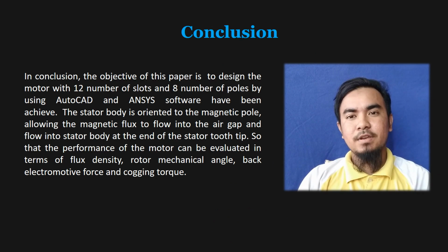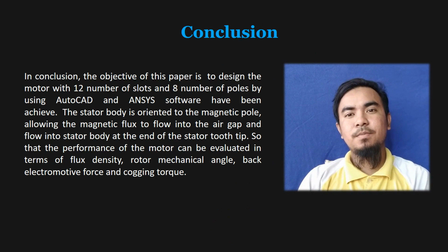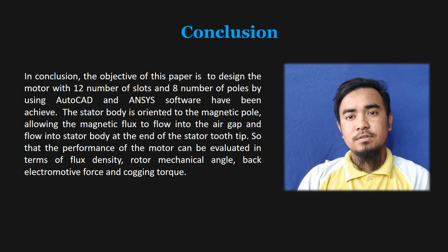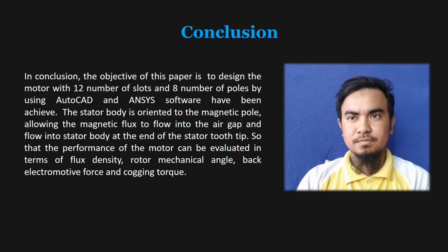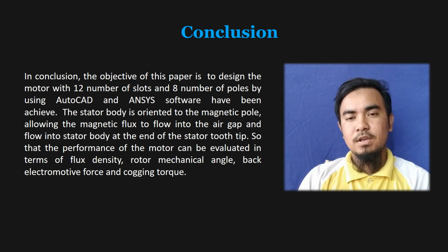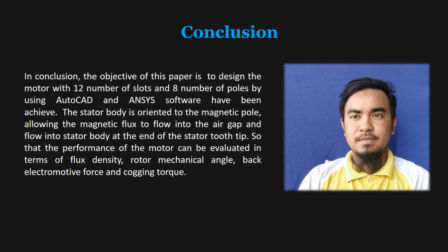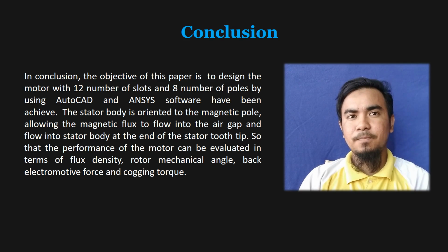Conclusion. In conclusion, the objective of this paper, to design the motor with 12 slots and 8 poles by using AutoCAD and Ansys software, has been achieved. The stator body is oriented to the magnetic pole, allowing the magnetic flux to flow into the air gap and flow into the stator body at the end of the stator tooth tip.